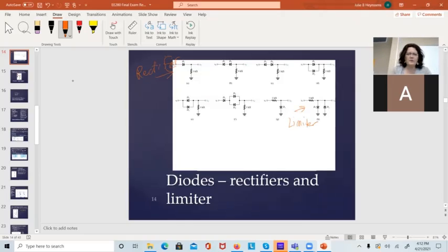So we want to look at how these respond to a sine wave. For the rectifier, the one I picked, we've got two conditions here. The input voltage, Vn, could be greater than 0.7 and Vn could be less than 0.7. Now, if Vn is greater than 0.7, the diode will be on. And that means that it's going to act like this. This is Vn. It will be a 0.7 of a volt battery. A positive goes the other way.